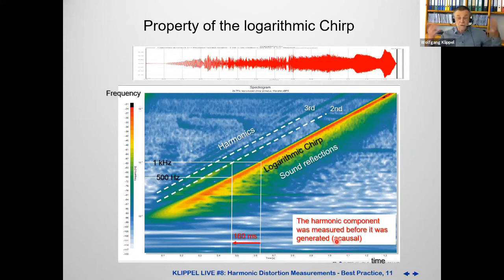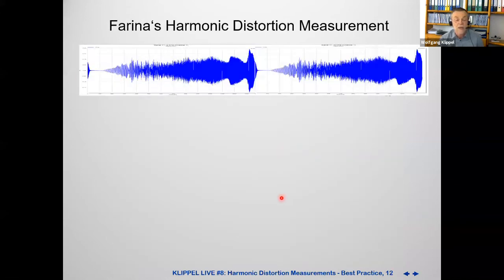So that comes because we are generating harmonics. The third harmonics will be at a higher frequency, so it will arrive even earlier than that. What does that mean? If we are playing our chirp twice, usually we have to do it because this speaker, here the JBL Bluetooth speaker, has a time delay, a latency of 20 milliseconds. So usually we miss a little bit the end here.